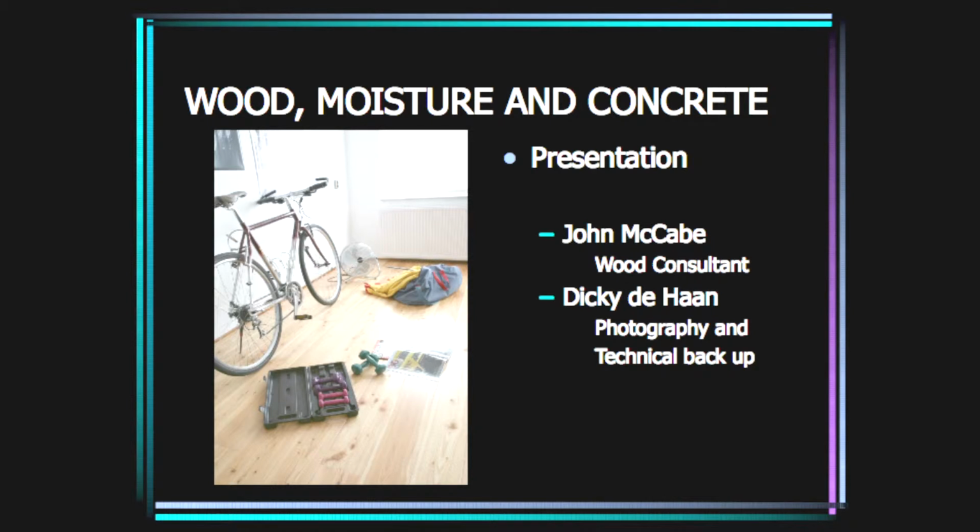Looking at wood, moisture, and concrete. Actually, 90% of all the problems with wood floors is related to moisture. If you eliminate the problems with moisture, you eliminate 90% of all of the problems with wood floors, which is enormous. It's a really important part of wood flooring.